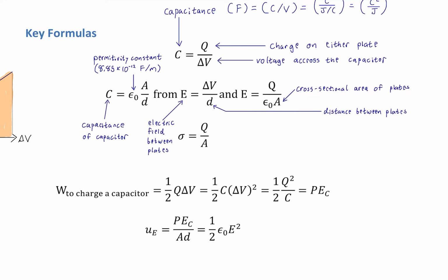Okay? All right. So I said I'd get back to electric field, and that's because here I'm saying that this is how we determine capacitance, how we actually find capacitance based on area and distance between the plates. Again, how we build a capacitor. But the reason it works is things we've already seen in the previous 3 lectures. Because after all, electric field is defined as voltage over distance, right? Absolutely, it is. I mean, the first time we saw it, it was force per coulomb, right? The units of the electric field were newtons per coulomb.